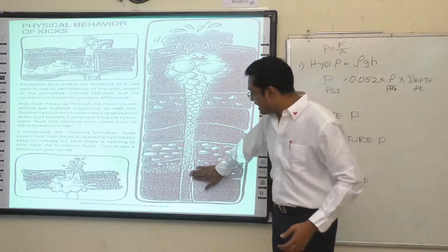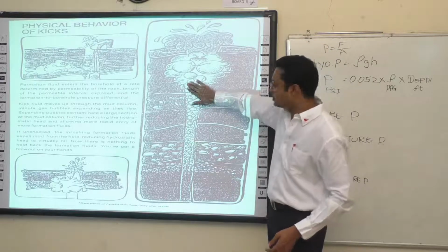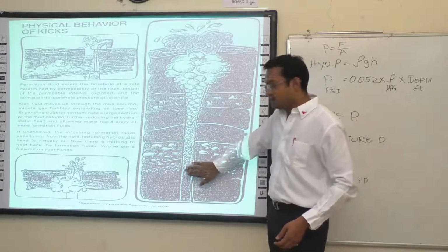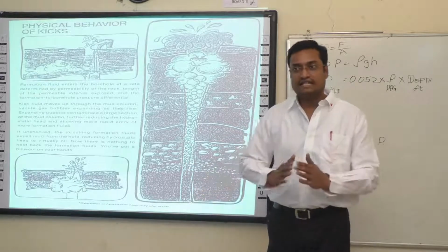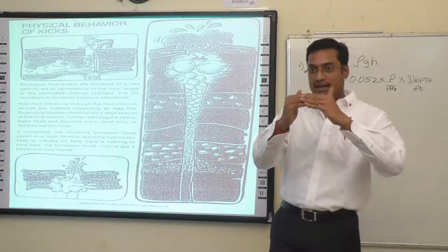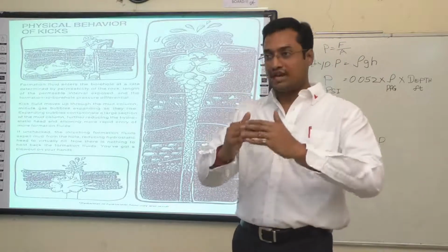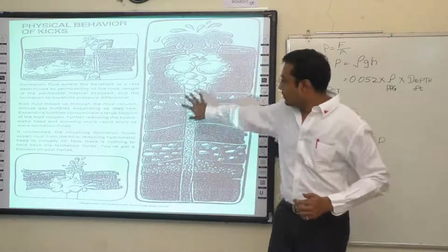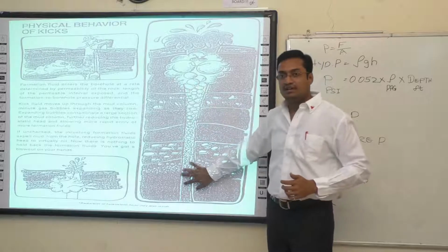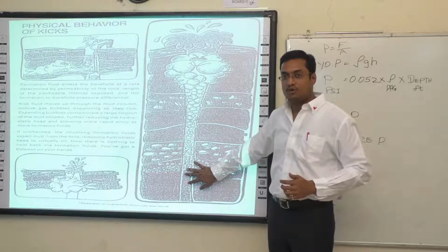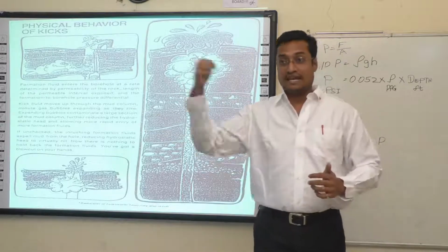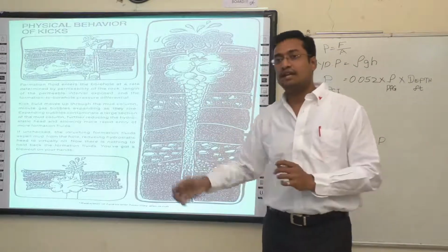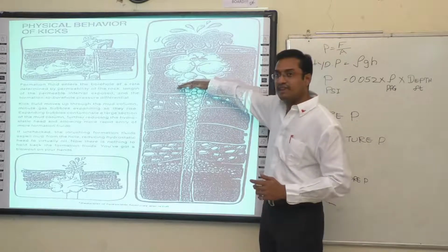Because it is bringing the same pressure from the bottom to the top, the bottom hole pressure will start increasing. If you close the well and don't allow the kick to expand, that will take care of the bottom hole pressure. So the overbalance condition will be regained without doing any well control methods. You close the well.